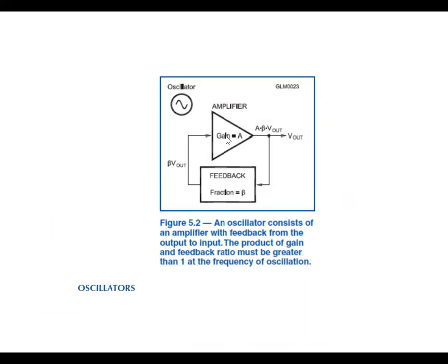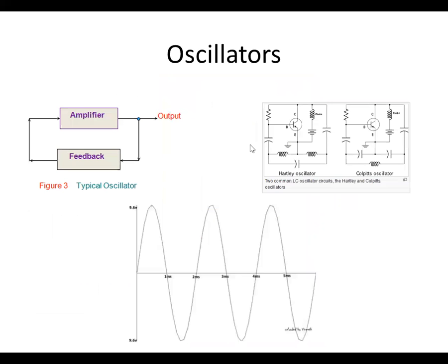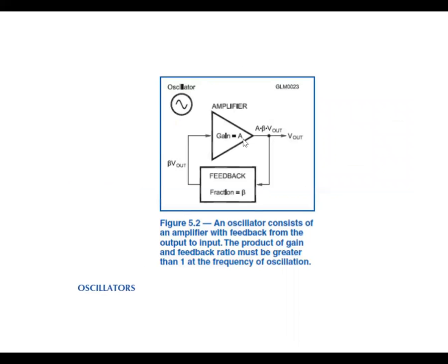They're used in building oscillators because they have a very high gain capability, and then you provide some feedback to make the oscillator work. So it doesn't have to be a transistor, but there does have to be an active device in an oscillator. By active device, I'm talking about either transistors or op amps.